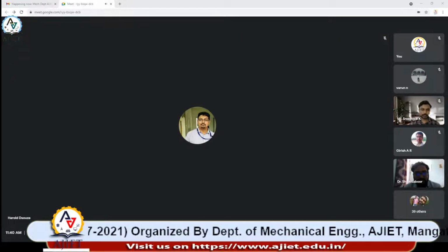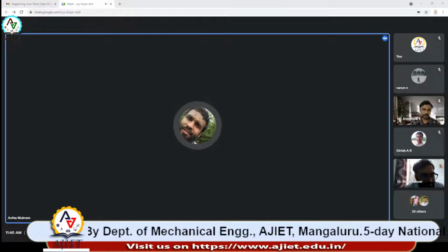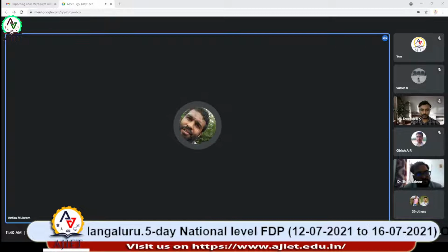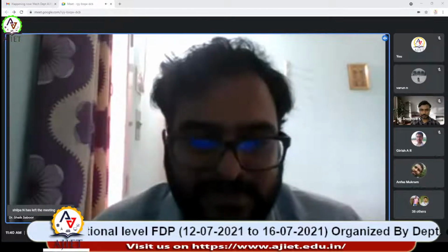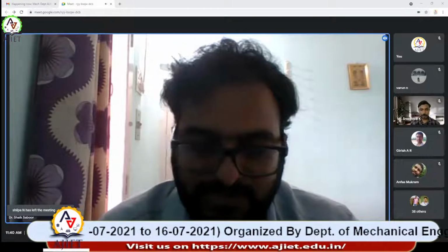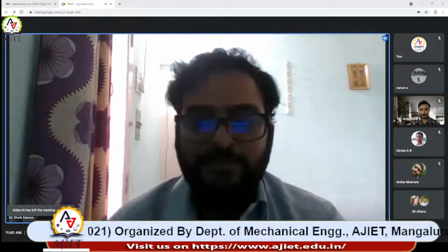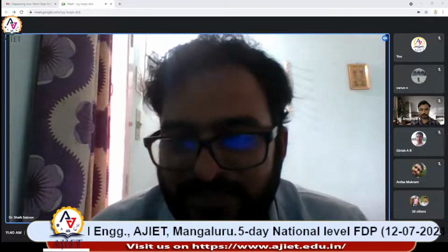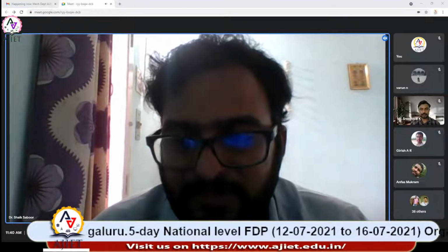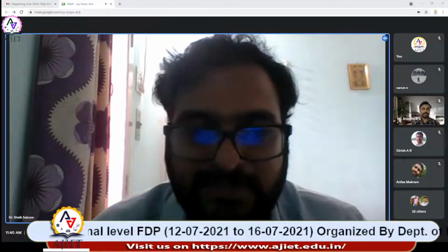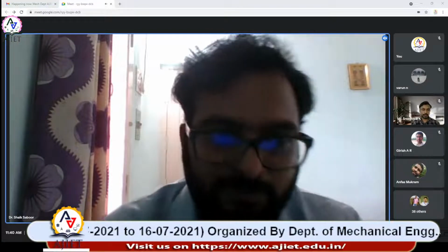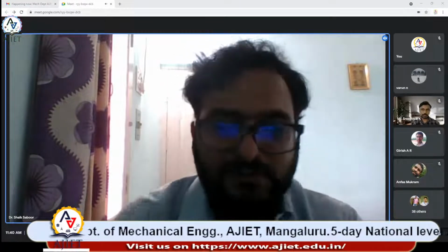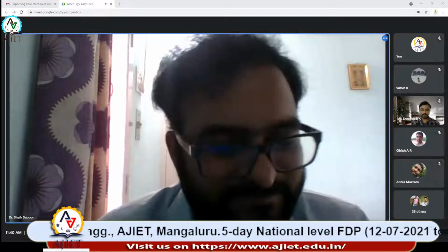Sir, one more thing. Regarding glazing materials, you are telling us about smart materials. Can we combine glazing with PCM materials? Is it possible? Yes, I think we have carried out those studies also, but we haven't put them in this particular topic. We tried with phase change material. Instead of air, we replaced the air with the phase change material, and we saw the performance, and we reported that study also. But we haven't shown it here in this presentation.